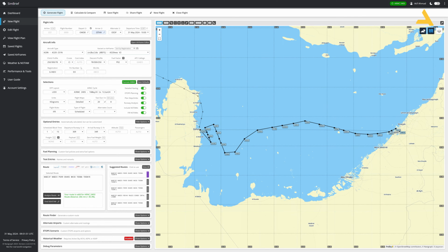It's the cost index. It's actually a number which determines the rate of fuel burned during the flight. So if you go with a small number, less fuel is burned, plane goes at a slower speed, but the range of the plane increases. And if you enter a big number, let's say 70, 80 or 90, the plane goes at a very high speed, but the range of the plane decreases because it is burning more fuel. For this plane, I'm using the cost index of 30.